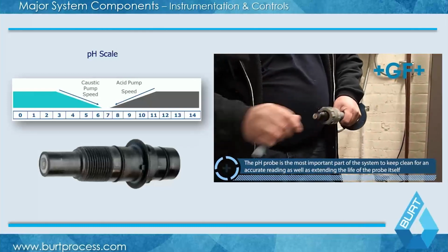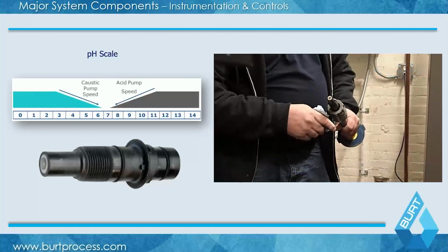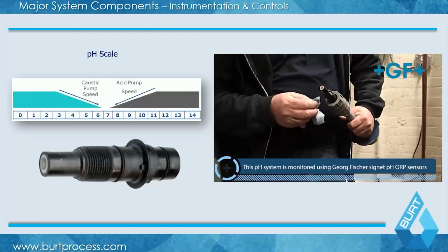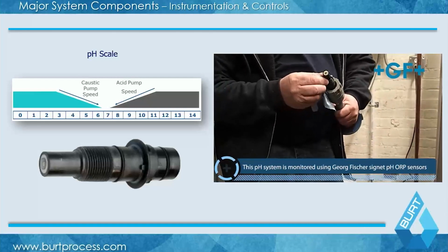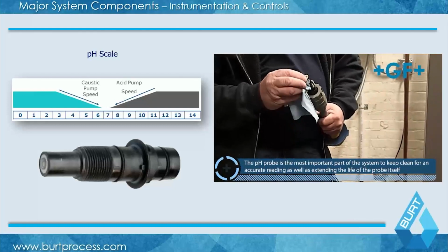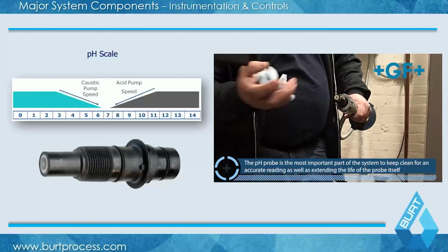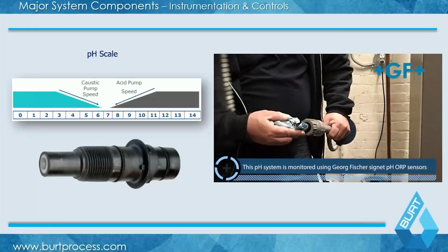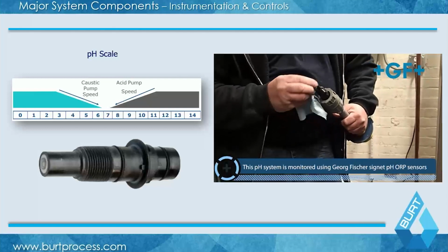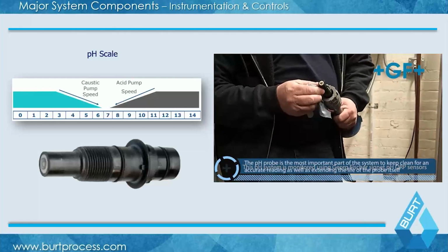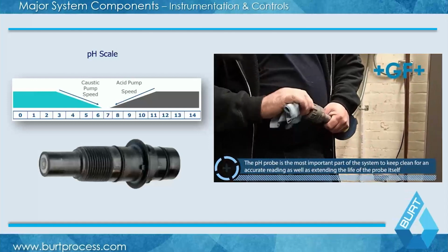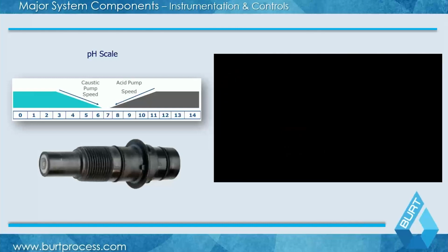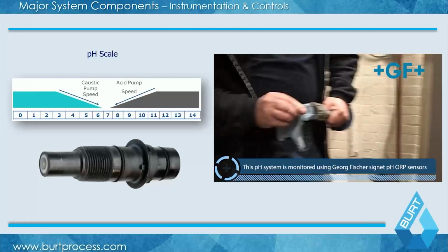There are a lot of different pH probe designs out there, some designed for high purity water, some for HF environments, and some that have actual cleaning apparatuses associated with them. Because you can have all these large tanks and mixers, but what's really the linchpin of the whole system is keeping that pH probe in operation. I can't tell you how many times I've gone into a facility and seen them pull the probes out covered with stuff, and once they're cleaned the pH reading will change by a matter of 5. So it's important to have that as part of your system.